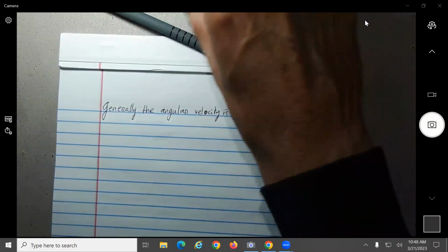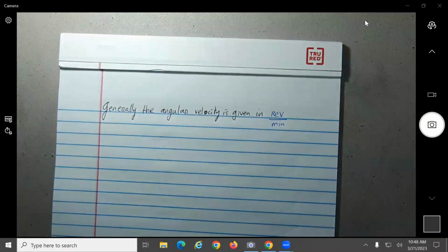When you look at the gauges in your car, do they give you radians per second? They give you RPM, no? So revolutions per minute. So basically, when you design a shaft, it's also revolutions per minute. So I'm just going to do a change of units here. And generally, the power, they can give it to you even in kilowatts, but sometimes they can give you that in horsepower, no? Okay, but let's just change this one.